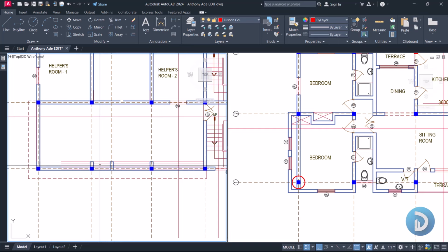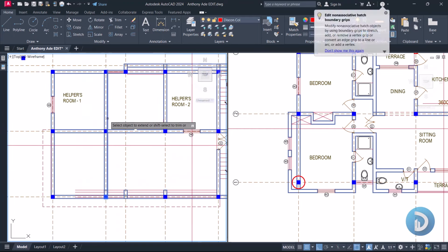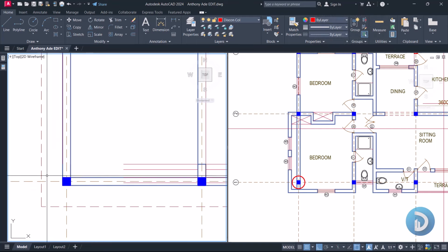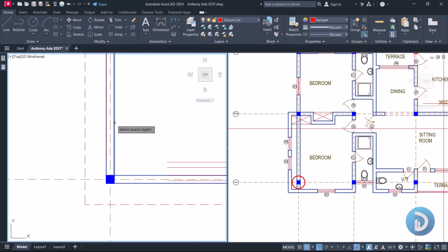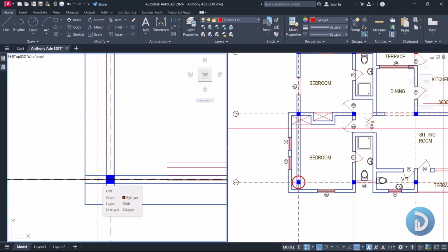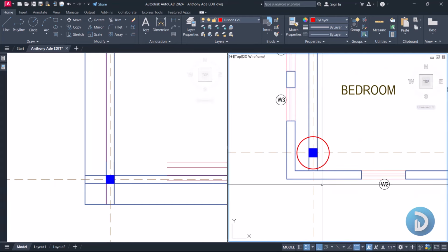Okay, I will extend this as well. I will extend this as well. So we'll have this other part of the beam to cantilever to this additional part. Let's match the properties so we have the same properties. So we'll extend this to this part. Then we'll also extend this to this part. So this cantilever is what will carry this column here and also carry this column at this end. That's if we decide to distribute this column both to the left and also to the right.